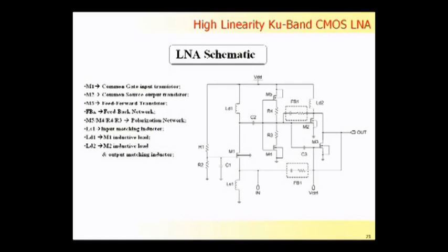Here M4, M5 with these two resistors have been designed to polarize the output stage. Here we also have LS1, the input inductor for the input matching, LD2 for output matching, and LD1, the inductive load of the first amplification stage.